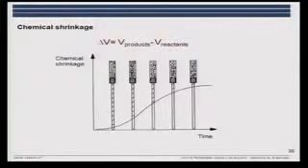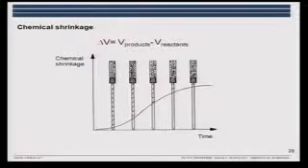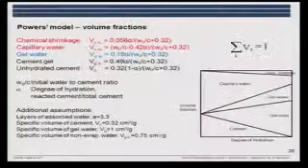Here you have put the samples upside down, but you can see that you can actually measure it where you have the paste and then a capillary tube, and you follow just the decrease in the meniscus of the water level. And you can do it continuously. And the chemical shrinkage is due to the difference in volume between the reactants and the products.